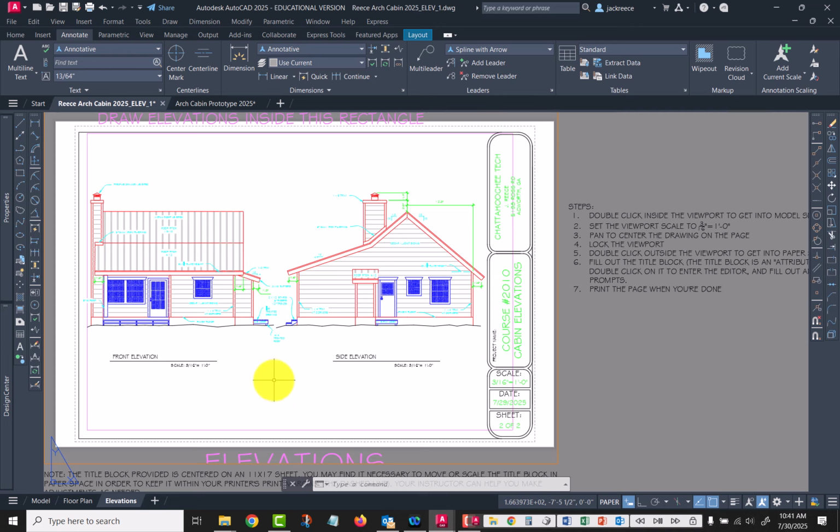In the publisher videos, when it starts out with the textbook and the publisher videos, they're drawing the framing lumber for the wall as actual size, 1.5 by 3.5 for a 2x4. But then when they get here to do this porch and the steps, they're drawing it nominal size.